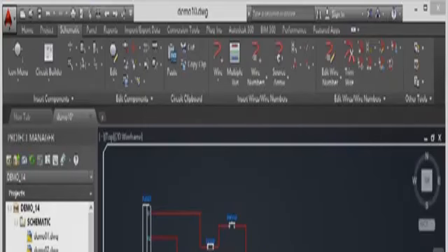So once you create all of these smaller circuits using your point-to-point wiring diagrams, you can reuse them over and over again. You don't have to keep on creating them in your AutoCAD electrical drawings. Once you've saved your point-to-point wiring diagram as a circuit and saved it out as a W block circuit to another DWG file in a known location, you can just insert those W block circuits straight into your AutoCAD electrical drawings. And what's really nice is it brings it in, and then all you've got to do is tag it and go through it and make sure that the numbering is tidied up afterwards.